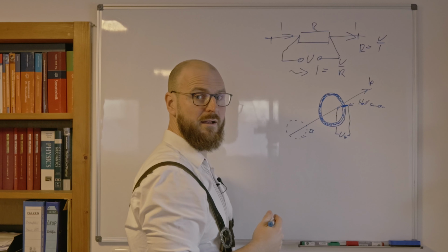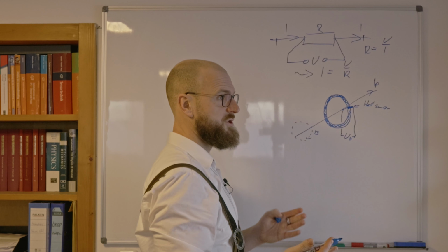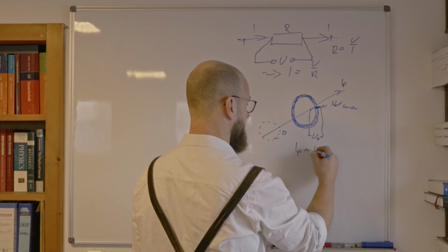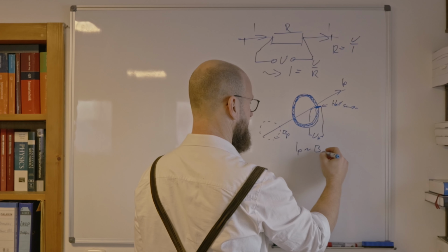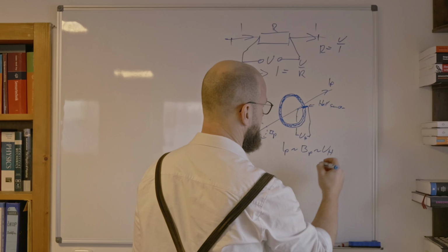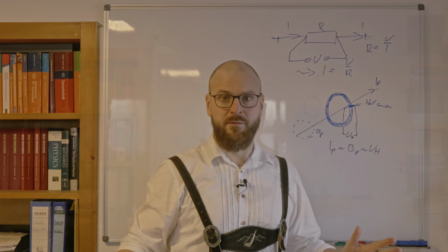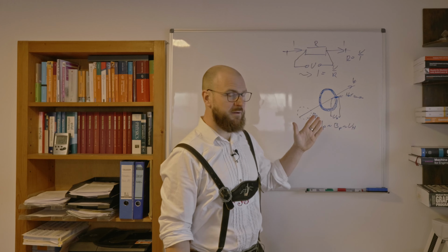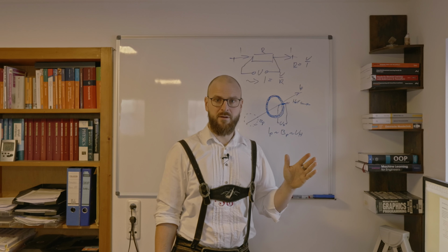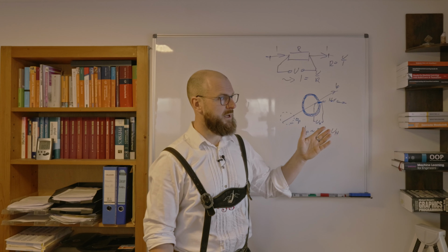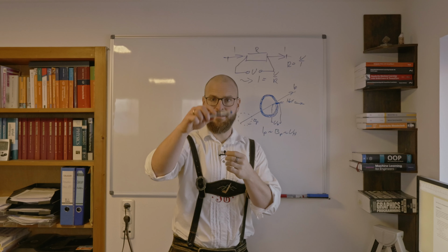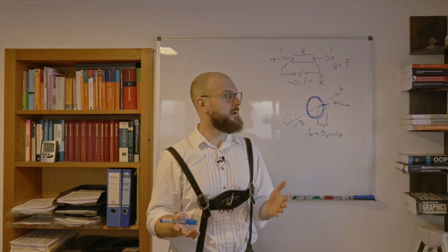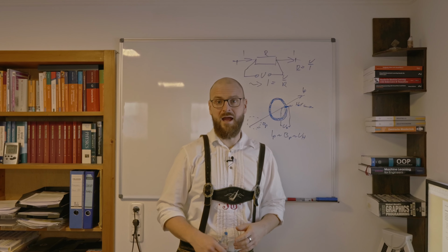And by that get a direct measurement, a direct proportional value for the current. So the current is proportional to the exerted magnetic field, which is indeed proportional to the Hall voltage. Awesome. Now we can measure currents not touching the system. Coming back to that example of the machine, there's the wire connecting the machine. We just close a ring around the wire which drives a machine and can measure the current indirectly, having galvanic